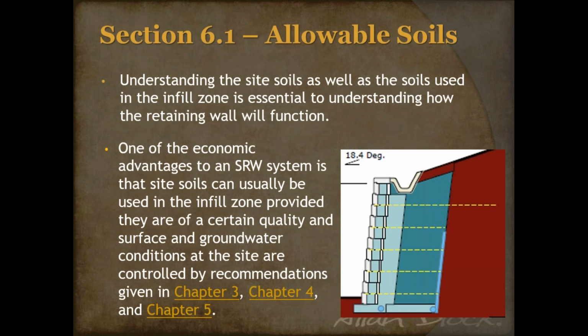That saves money. You don't have to bring soils in. You don't have to haul soils off. And so if we can use the on-site soils during the construction process, that helps. And that is key because that can only happen if you are handling the water properly, or if you've got compaction there as well. And so there is huge emphasis, and that's why we come back to chapters 3, 4, and 5 for that water management.